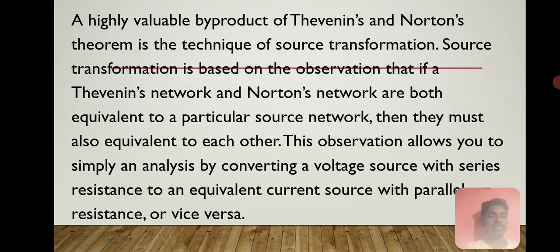A highly valuable byproduct of Thevenin's and Norton's theorems is the technique of source transformation. Source transformation is based on the observation that if a Thevenin network and a Norton network are both equivalent to a particular source network, then they must also be equivalent to each other. This observation allows you to simplify an analysis by converting a voltage source with series resistance to an equivalent current source with parallel resistance, or vice versa.